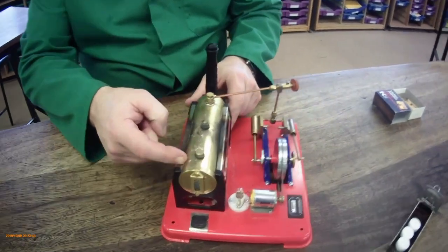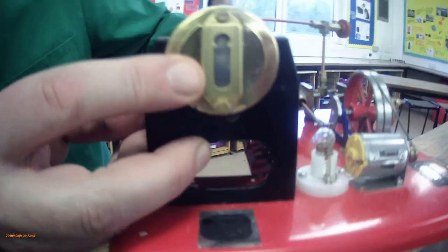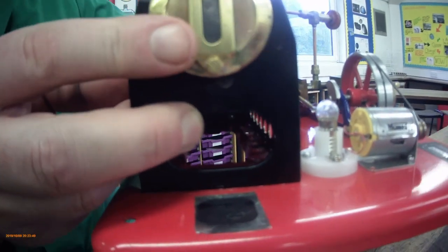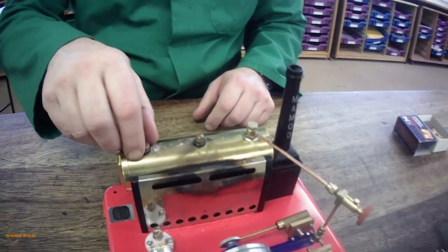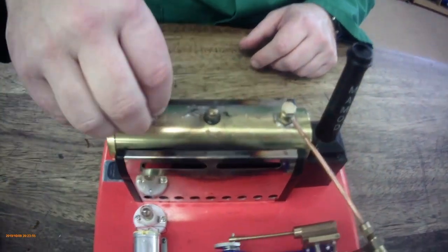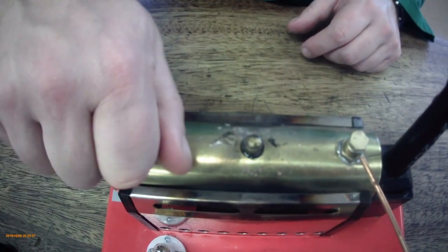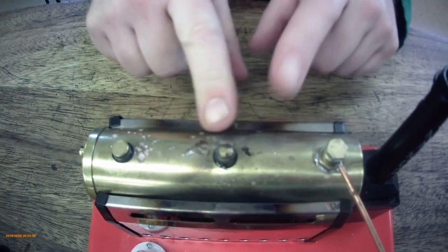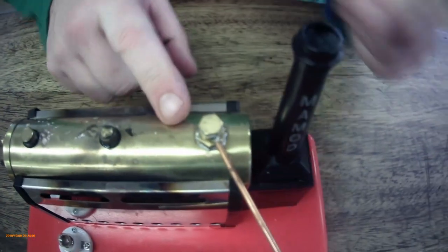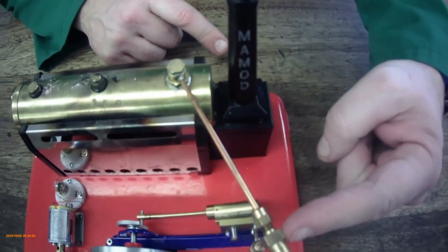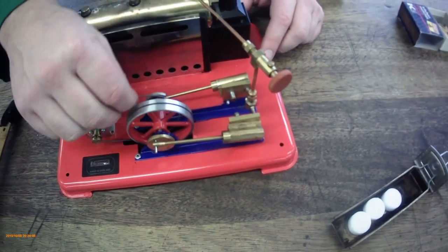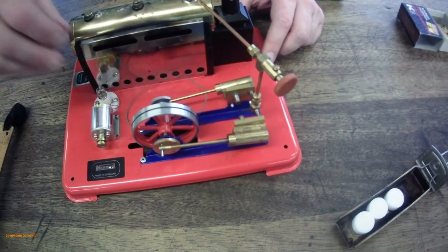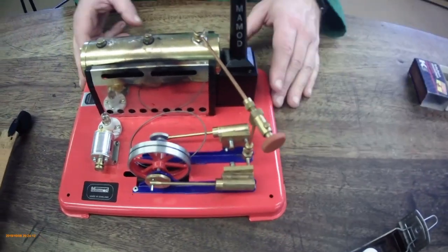So if we turn it round, here we've got the cylinder. Inside here there is water. You can see that sloshing around slightly. There is the water there. Now, in order to get this to work, you put the water in there, and you've got a valve on the top here. So that valve will be a safety measure that will stop the steam pressure getting too high. Any steam that is able to will push through, push those two pistons, and enable the wheel to turn.